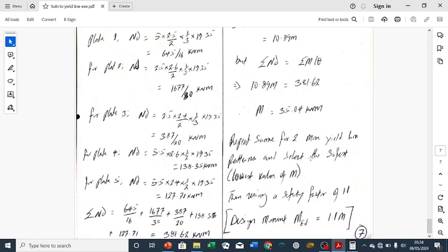So in this example, we are not going ahead to do the other two yield line patterns. So you repeat the same for two more yield line patterns. When you repeat them, for the value of M that you have, you select the safest one. The safest one is the lowest value of M that you will have from the three yield line patterns. When you have the value, you use a factor of safety of 1.1 and multiply by that M to have the design moment. That means the design moment, which is MED, will be 1.1 multiplied by your selected M, and your M should be the lowest M you have from the three yield line patterns.